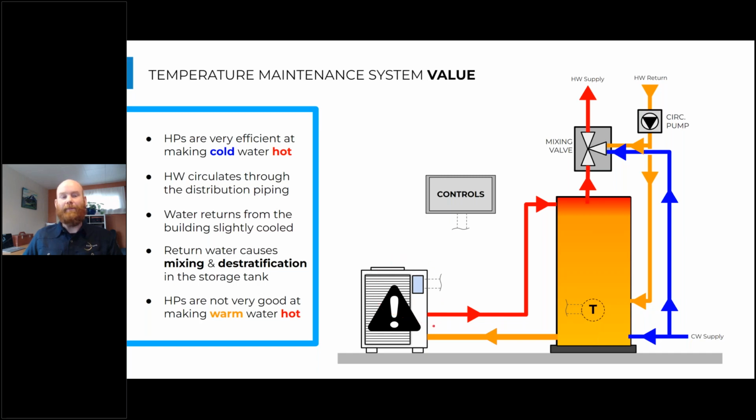And why is this happening? Well, the single pass heat pumps are operating in a single pass heating cycle, and the components, the evaporator, the compressor, the condenser, are all sized for a typical range of operation. And when we return warm water back to them, and it's a very cool ambient air condition, that's when we start to run into issues and alarms with these heat pumps. Their components in a single pass heating cycle weren't necessarily sized or designed for that application. We can only do it in a limited amount.